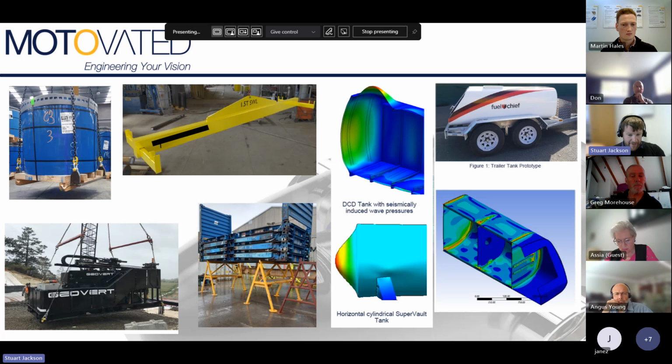The trestles, for example, were quite interesting. Somebody had made those at some point. The customer had a number of different types and different styles and different section sizes, and basically what it boiled down to was doing some fairly simple calculations on the frames as they are, with a 2 times working load limit, and then physically loading them up to that 2 times working load limit.